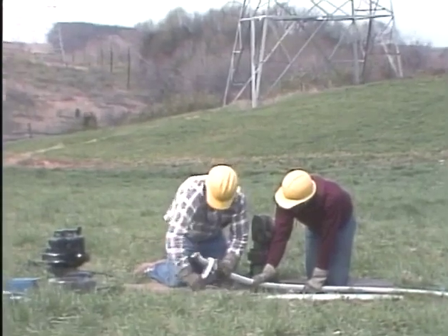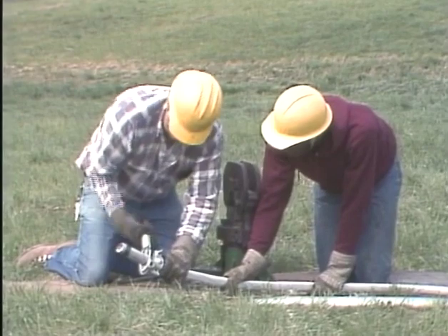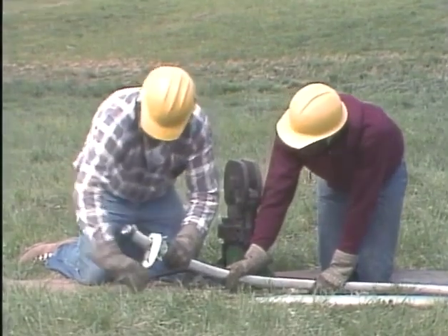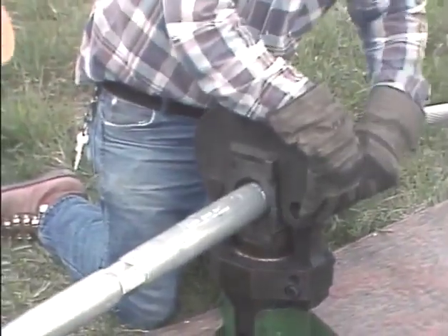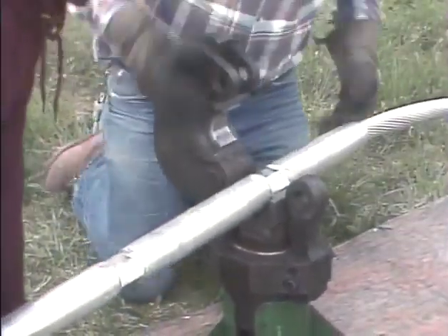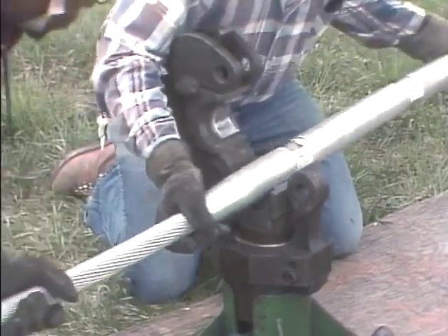So, we've seen that using conductor bundles can reduce AC resistance caused by skin effect. We've also seen how the material that a conductor is made of affects its resistance, and how conductor length affects resistance. In your job, be sure to follow the specific procedures for repairing transmission lines, replacing or installing connectors, and making splices. Improper procedures could lead to a high resistance connection on connectors and splices. This will increase the resistance within the transmission line and also increase power loss.